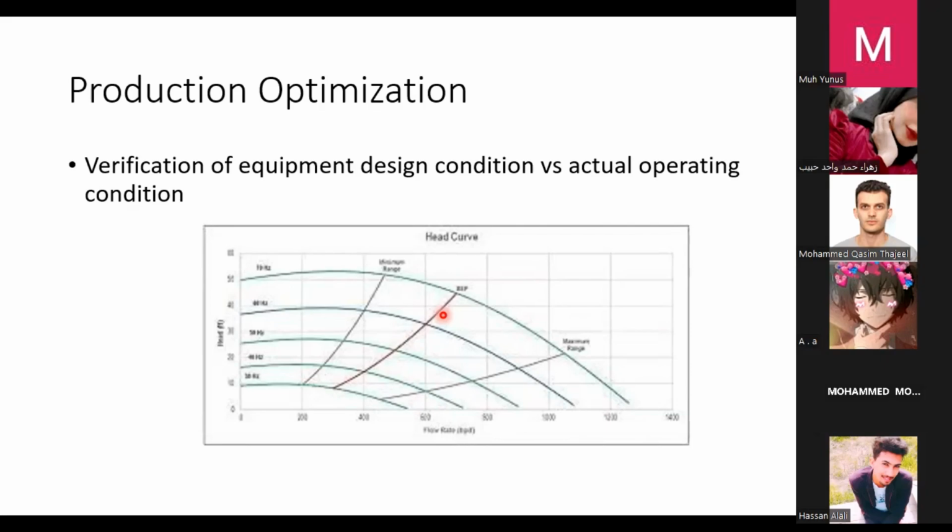It depends on the flow assurance study. You know that when we start production, we have to do the flow assurance study. We need to produce within the range of pressure and temperature. If we are out of this range, it will cause some flow assurance issues like wax. To avoid this, if we face this issue, we need to inject some chemicals within the pipeline, or in the bottom hole if we have natural flow, so that will reduce the amount of wax or any debris.